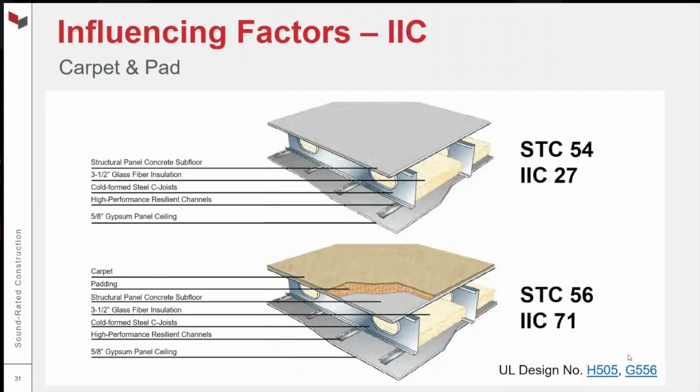You've made a cushion, right? When the hammers on that little tapping machine drop, they're not generating a lot of energy because they're landing on a cushion. So carpet and pad is extremely influential on IIC. If you want to guarantee high IIC, use carpet and pad. But recognize that carpet and pad is not always in fashion, not always an option.